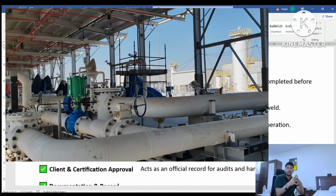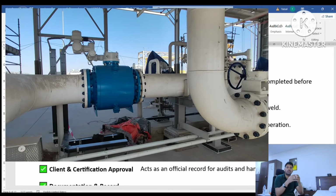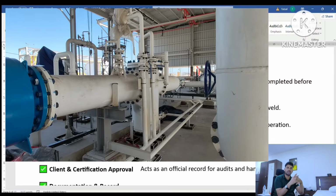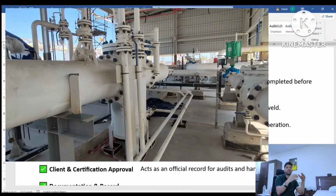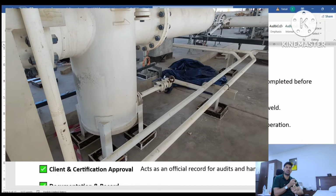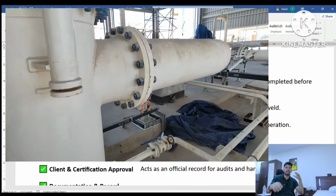Traceability means maintaining the complete record for every line and every single joint. In this test pack, how many joints there are, and all the joints have welding completed, NDT completed, all visuals completed, and all the non-destructive testing completed.